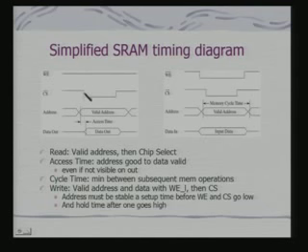The chip select is basically selecting the corresponding IC or the memory module for the purpose of reading. The address is provided on the bus. The decoder would be typically part of the memory device itself for selecting the row. So, once I have selected the corresponding memory module and I have provided the valid address, the row would be selected, and after that you will be expecting the data.